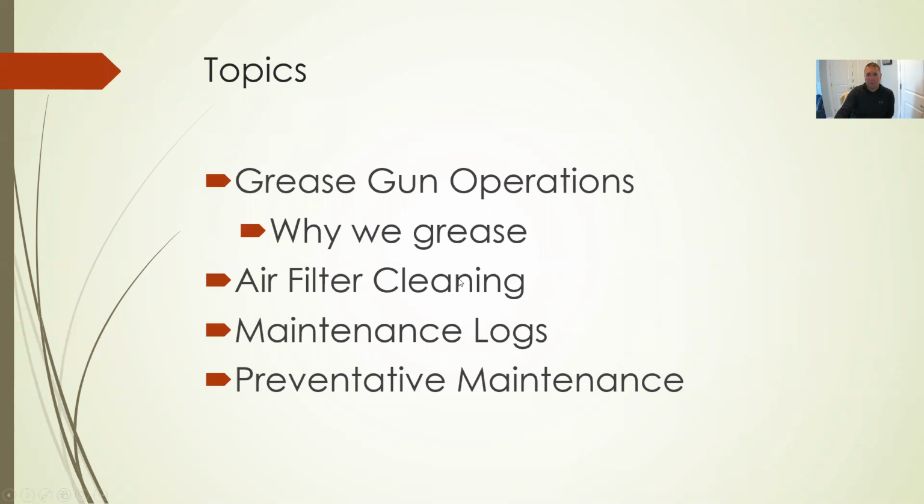So some of the things we're going to talk about today: greasing the machines, why we grease, and a little clip on what that grease fitting actually does, because that's part of the maintenance of these pieces of equipment that we operate. They have little grease fittings, and you make sure they're greased properly, along with cleaning out the air filters, changing air filters, making the maintenance log, and just doing your preventative maintenance in general. Preventative maintenance is all of those things in general.